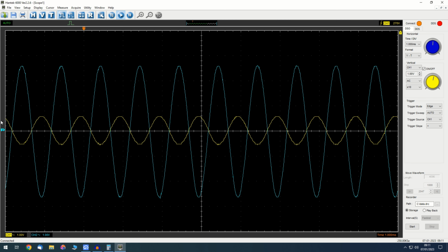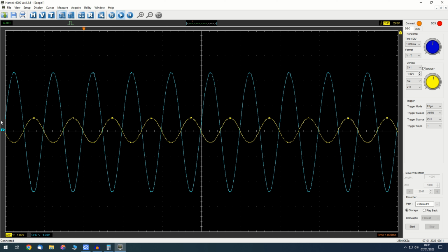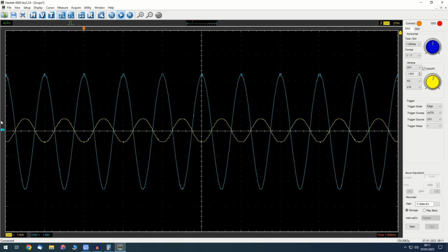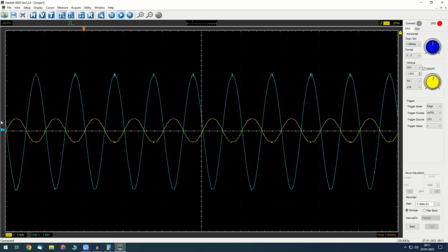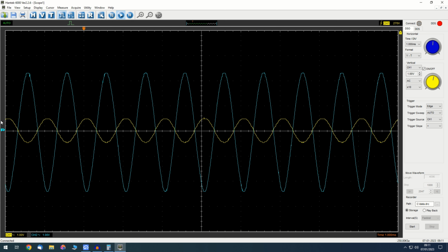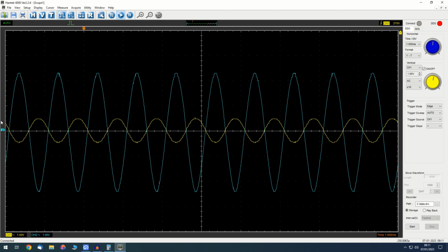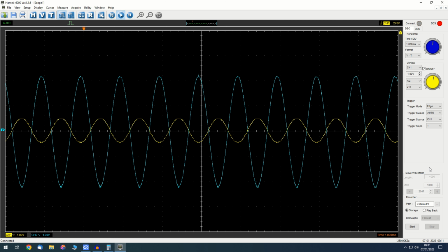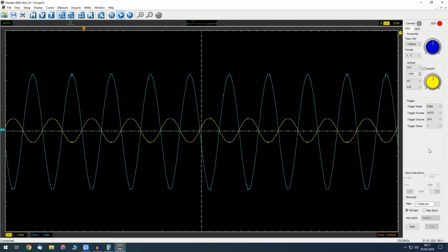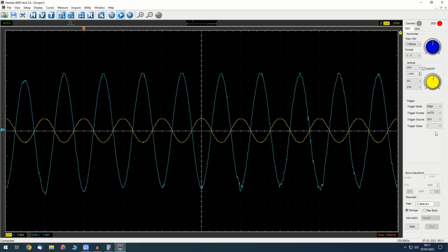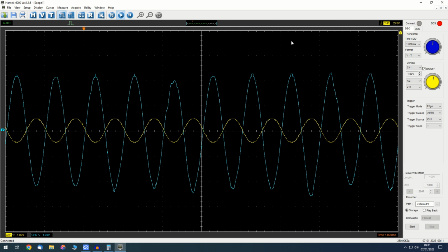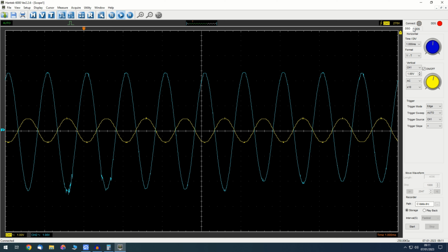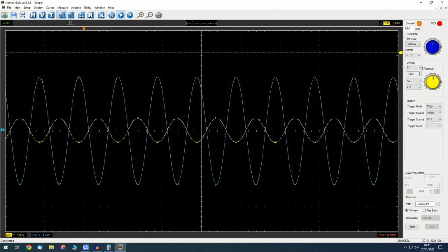The waveform's obviously a bit lumpy just from the screen display, but with that set to roughly positive and negative half a division on screen, let me just have that. I don't know where the trigger is. That's why it's drifting. Let's just get rid of that drift. We can move the trigger into range.